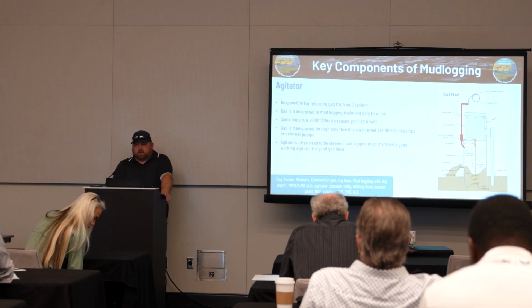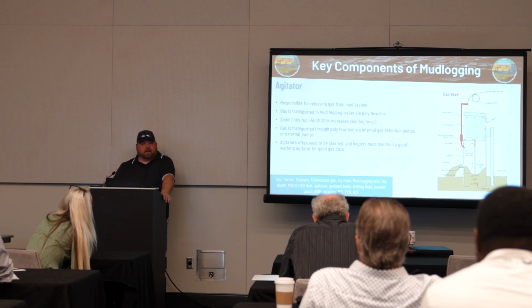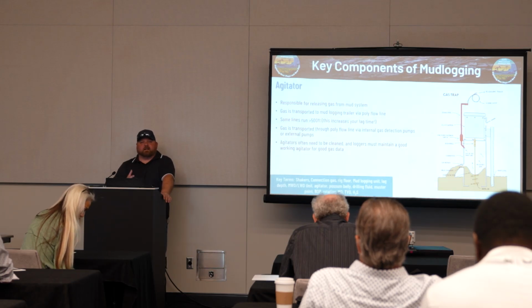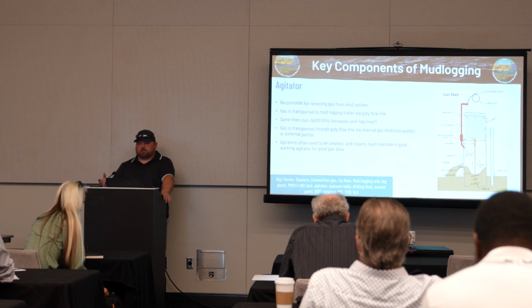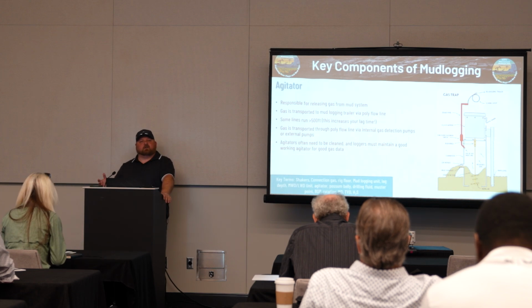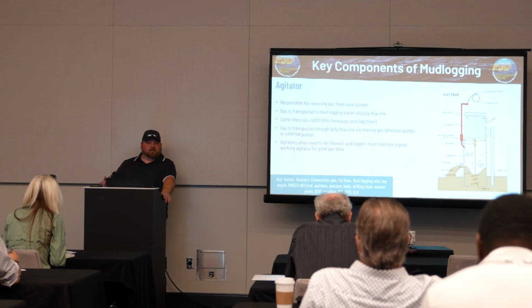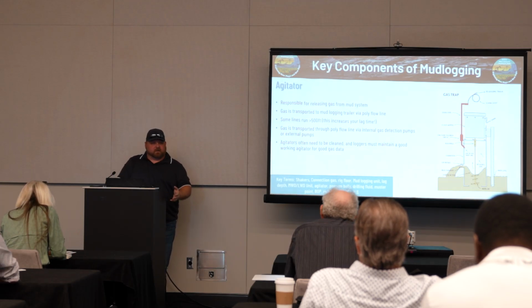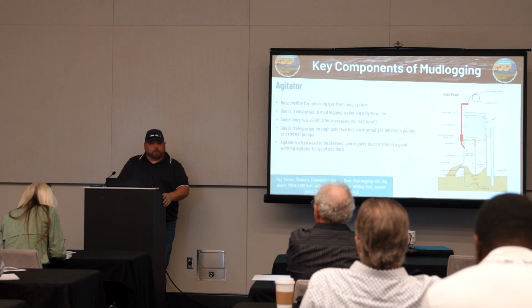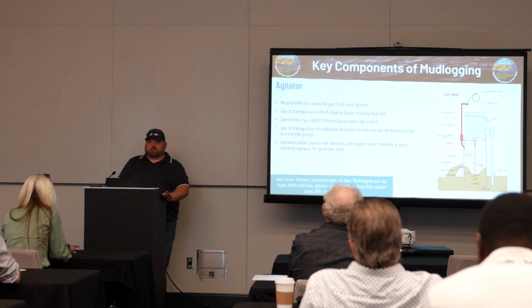You also want to clear out your possum belly. Cuttings are going to build up in that possum belly. It can't flow all the cuttings out all the time. And derrick hands, rig hands, they've got 100 other things going on on the rig, so they can't get to it all the time. So you've got to check your possum belly. If you have to, shovel it out. Typically, they've got a hose up there or something, and you can wash it out real quick. It takes 2 minutes. But that's just some of the maintenance that you have to do to make sure you're getting the most accurate readings you can.